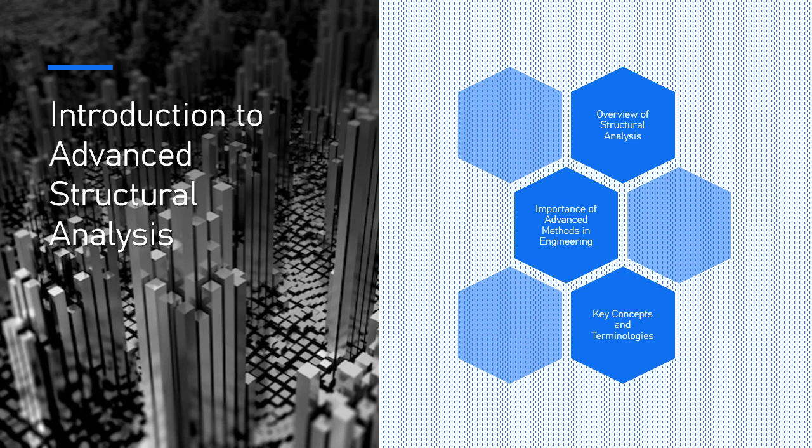1.10. Energy methods. Energy methods are used in structural analysis to calculate displacements, internal forces, and other parameters based on the principle of work and energy conservation. These methods include Castigliano's theorems, used to compute displacements in structures based on the strain energy.